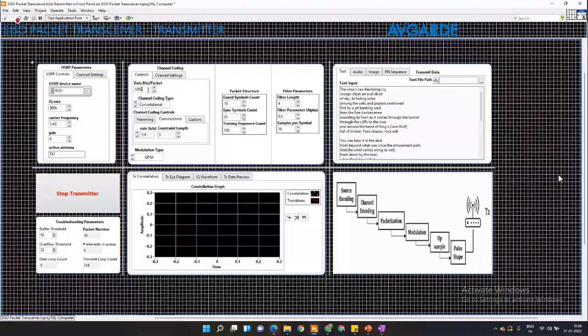So we can choose the number of data bits per packet. There is a limit. You can go from 1 data bit per packet to 8192. We've seen this range works pretty well, so we've selected this range. Right now, we have defined two of them having a convolutional code, and we have kept a separate blank portion where, if anybody wants to do a custom code, like one of you asked, LDPC or turbo codes, if you have a custom code that you want to build, you can easily place it over here and then execute it.